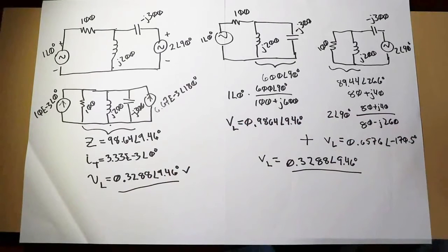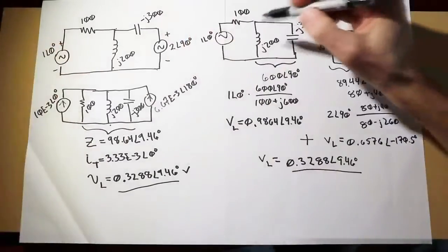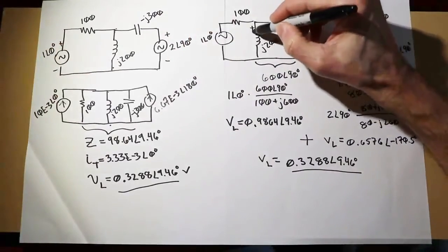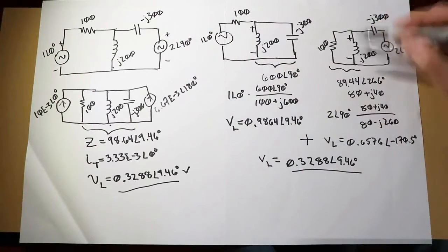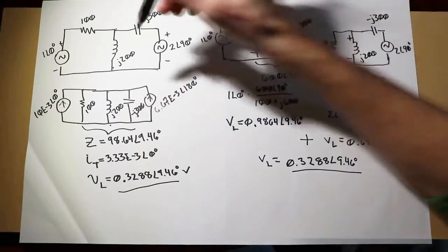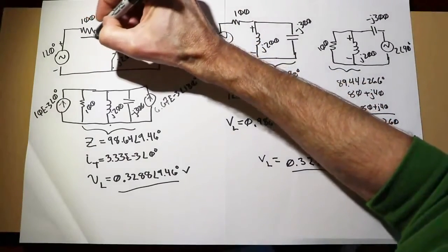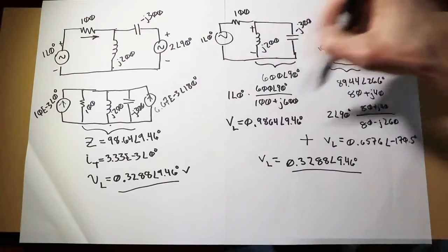Beautiful, right? Now, in this particular case, the two voltage sources happen to produce reference polarity on voltage like so across the inductor, plus to minus. We just straight add them up. Everything's very simple. We could also use this on current, not just voltage. So for example, if I was interested in finding the current through, let's say, the 100 ohm resistor, we could do the same sort of solution over here. It'd be a little bit different.